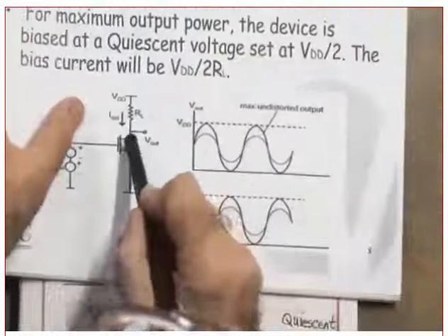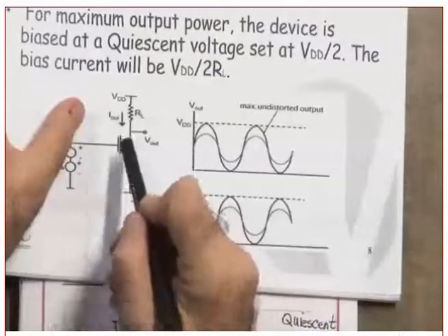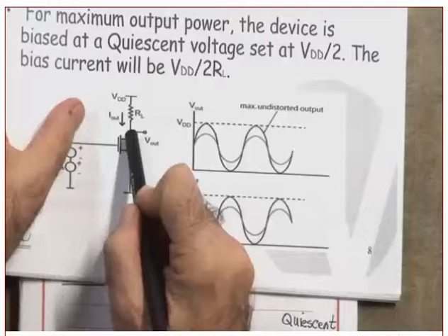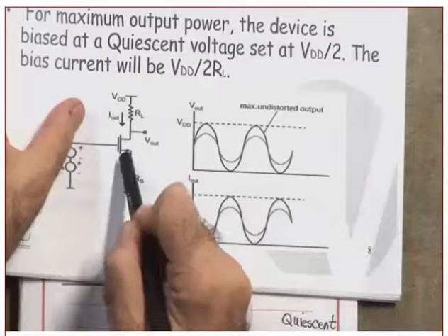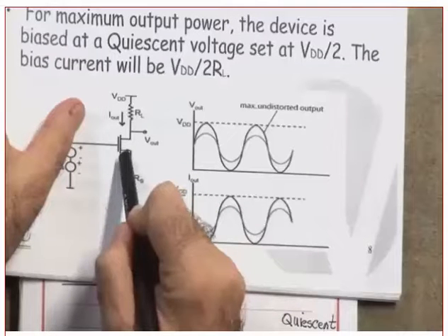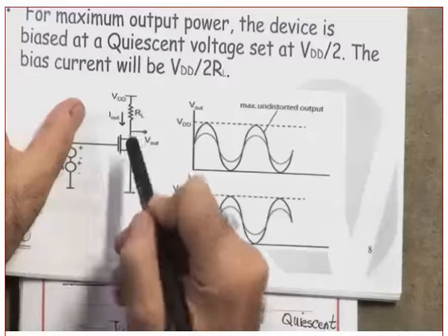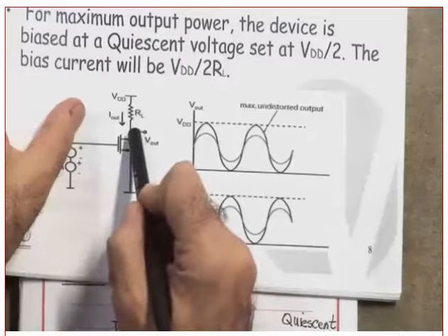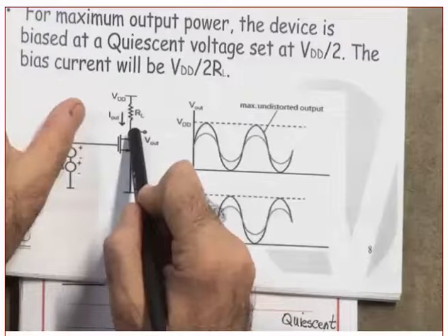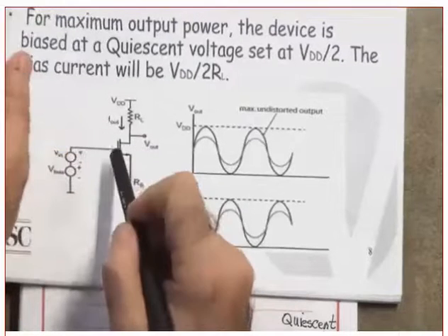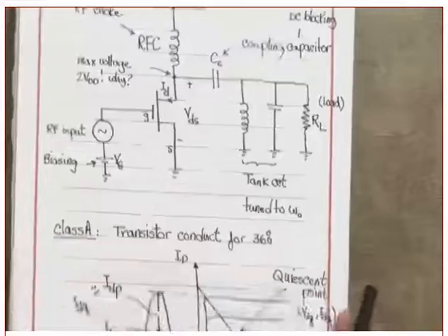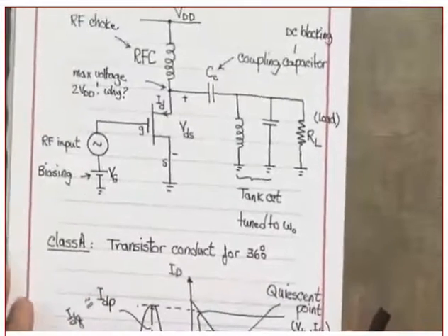What is the voltage in here? Maximum. Maximum voltage in here is how much? Is VDD when the current is what? When there is no current. In other words, when the transistor is cut off, the voltage in here is a maximum of what? VDD. It cannot go more than VDD. Yes? No response. Okay. I want you to see this and to try to understand it carefully.